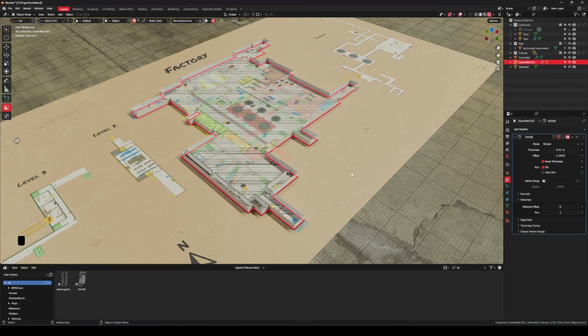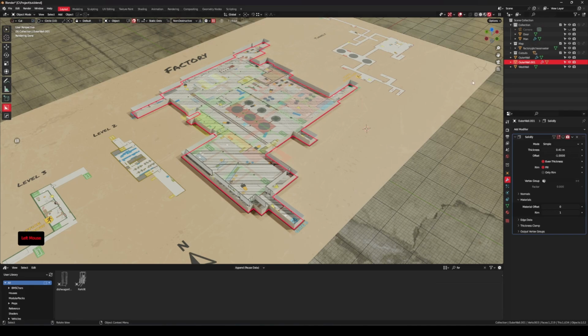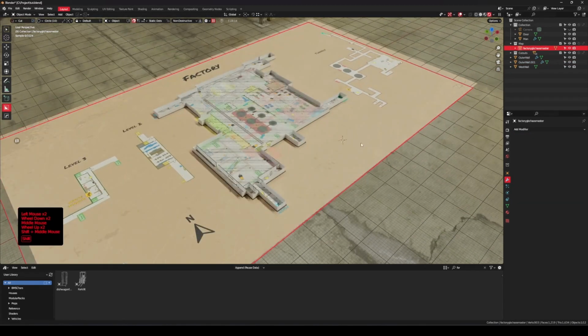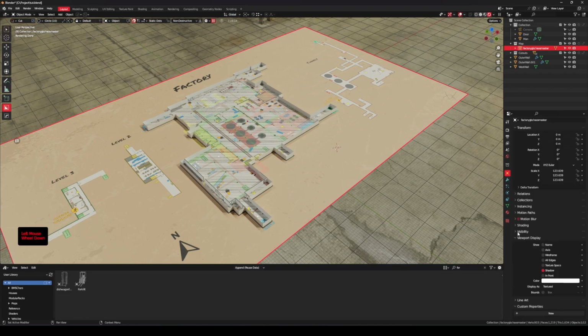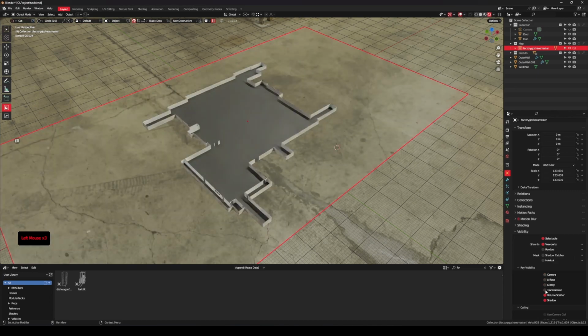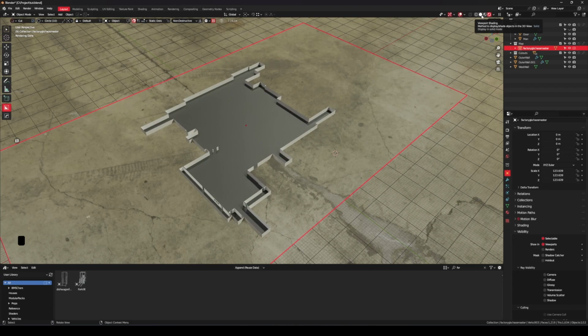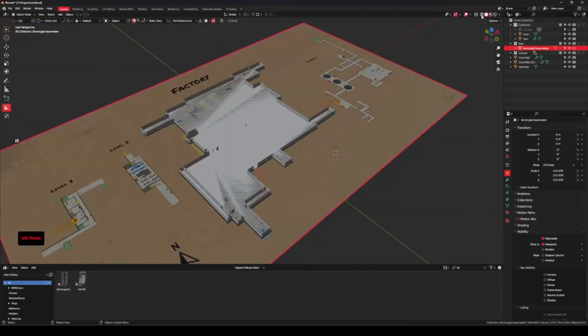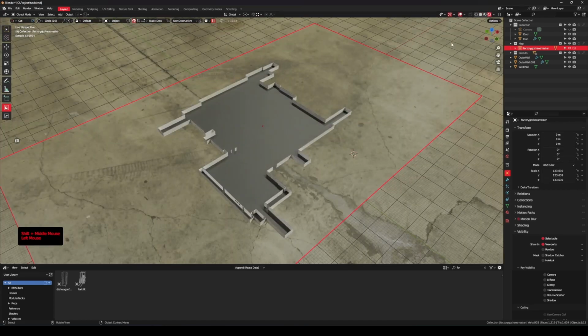Okay. Another thing you might want to do is go up here to map and enable the selection for the map again, or the reference, should I say. And go into object properties, visibility, and uncheck renders, and then all of these visibility checks can also be disabled. So now when we go back into the viewport shading, we can see the reference, but in preview mode we won't.